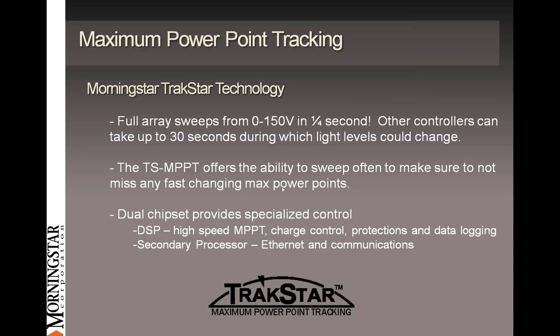The TriStar MPPT is going to give you the ability to sweep not only this fast, but if we see a large change in the max power point, we'll sweep a second or even a third time in just a few seconds to make sure that we did in fact get it right the first time. If it's changing rapidly due to some condition, we want to make sure we didn't get thrown off and sit on the wrong one. So we'll sweep a couple times to be sure. But generally on a bright sunny day, we slow down. We don't need to sweep as often because things are fairly stable.